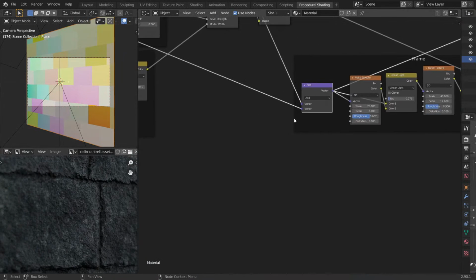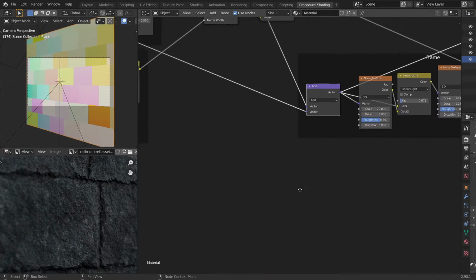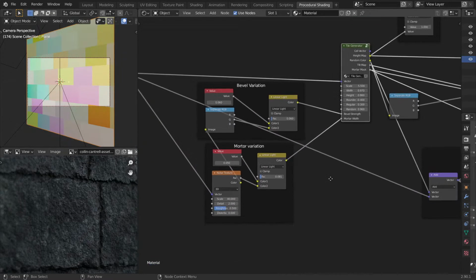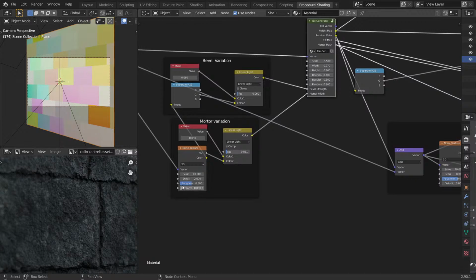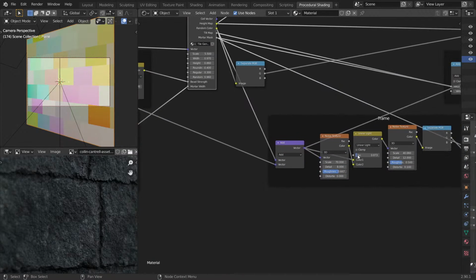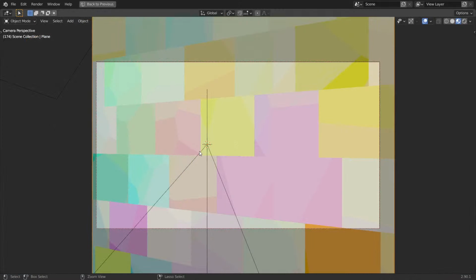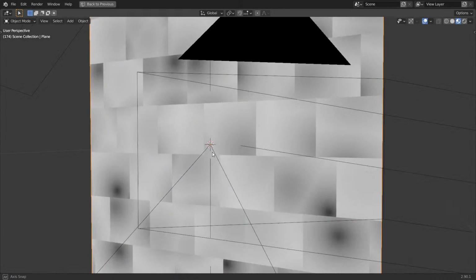And because the overall scale matters a lot, we'll keep things in scale. So let's change this to 40 exactly, and let's add a Voronoi texture. Let's connect the vector here and look at the distance.